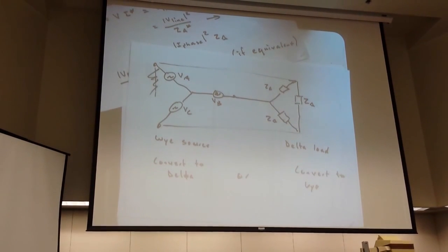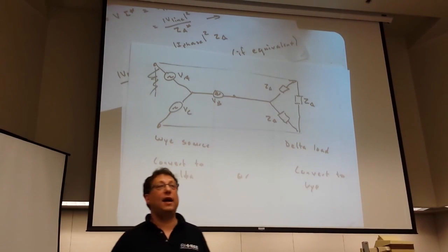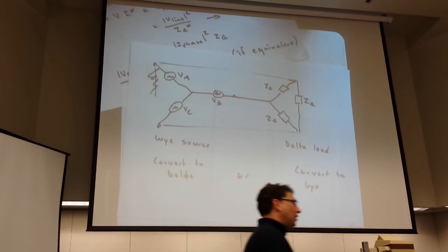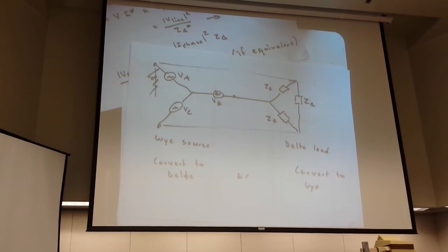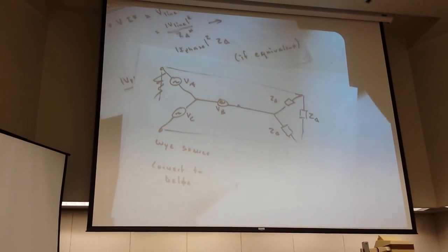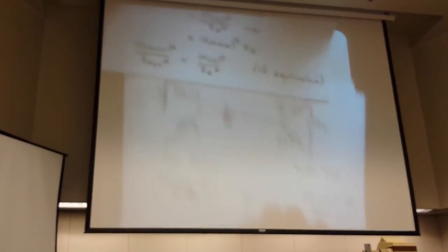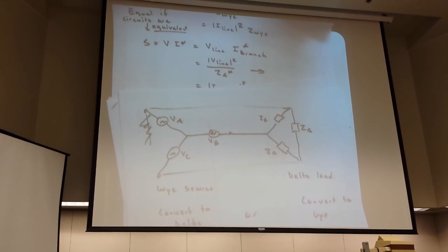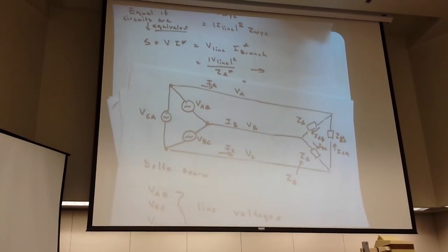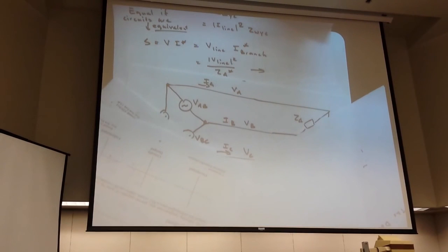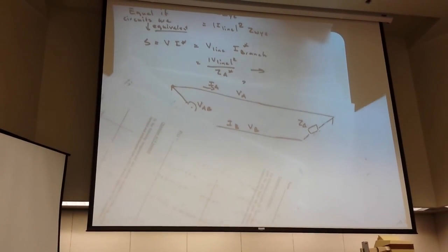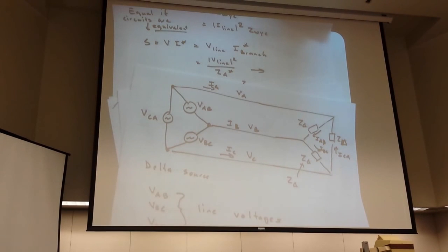Ultimately, this is three-phase. In my experience, it's not necessarily very intuitive, but the thing to recognize here is if we're looking at a balanced load, ignore the three-phase aspect of it. Ultimately, if we're talking about balanced loads, which is all we're talking about in this class, and I think all you'll actually talk about in energy systems as well, it's the same problem that we've done all along. It winds up just being three individual single-phase problems. If you want to study imbalanced loads, then go to graduate school.